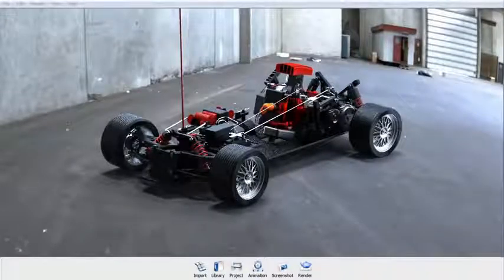The first thing to note is that KeyShot is an entirely CPU-based, standalone render engine for 3D data. Now, since it is CPU-based, this means that you're not dependent on the graphics card at all while using KeyShot. Any 3D data that you have loaded into the scene will be stored in RAM, and all the rendering calculations that occur will occur on the processors.